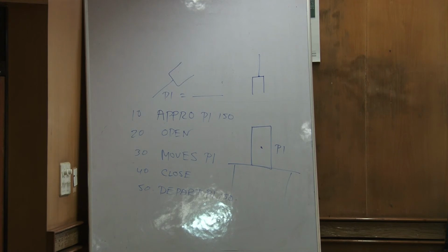Okay. Right. So if you want to make your cycle time more and more efficient, then you have to use commands which are the least time taking commands and not closed loop commands. Okay. So this one will give you an open loop command. So if the robot is somewhere else doing something else, when it is moving from there to here, you can open it. And if you are sure that it has opened by the time it has come here, then you can simply go ahead with this command only. It will take less time.